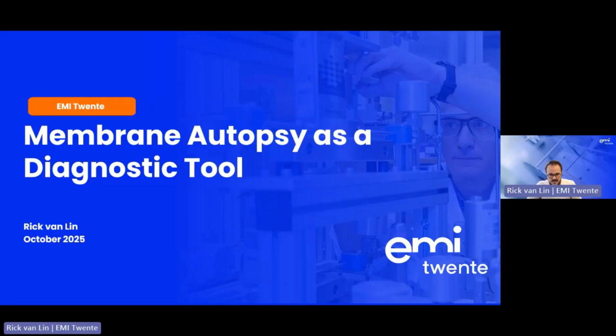All right, thanks. And thanks to Nieck for teaching us all about the mechanisms of fouling. And now I would like to share how a membrane autopsy is a great diagnostic tool to identify what type of fouling has occurred on your membrane, and potentially how to prevent this from happening.